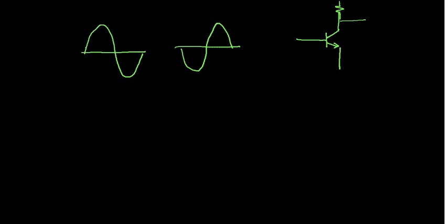See, what is the output voltage here? Whatever the main voltage, VCC or VDD, minus this voltage drop, that will appear there. More the current, more will be the voltage drop, and very little will appear here. But if there is less voltage drop, there will be more voltage at the output. In that sense, it's an inversion operation, right? So the simplest case was electronic. All these electronic devices, in simplest form, may act as this kind of switch or an inverter operation. So this was all what you learned last time.